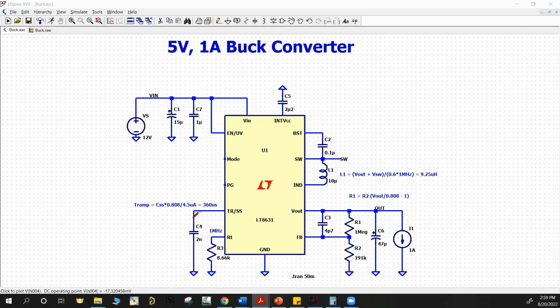But generally, you can omit this soft start capacitor, and what it does is force the chip to fully turn on and fully turn off without any delay. Obviously, there are going to be some delays because of the parasitics and because of the turn on of the actual FET, because the high side and low side MOSFETs have turn on time depending on how much charge they have at their gate. So it's never going to be instantaneous, but there won't be additional soft start ramp up time introduced to the switcher when you omit this particular capacitor.